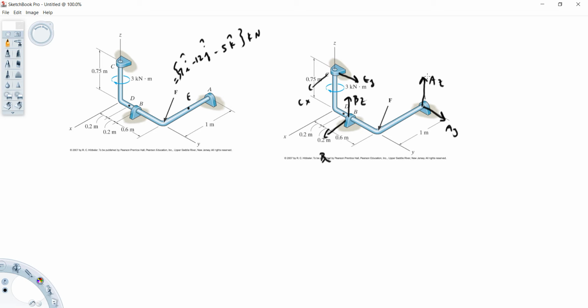Now, right now, there's 1, 2, 3, 4, 5, 6 reactions, and for this free body you can only write 3 force and 3 moment reactions. So we're limited right now. We can't write any more reactions. If it had any more, we wouldn't be able to solve it. This thing right here certainly cannot do any moment about the z-axis. Conceivably, it could provide some sort of moment about both the x and y axes, but you'll see a term used in a lot of these problems that says proper alignment.